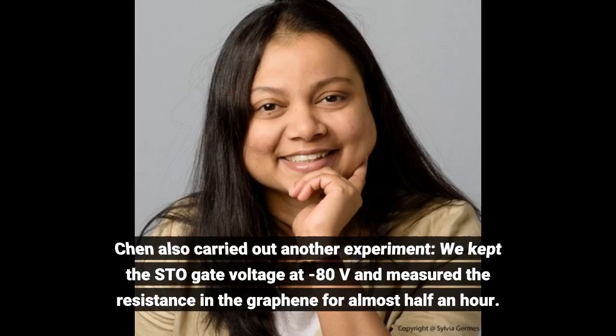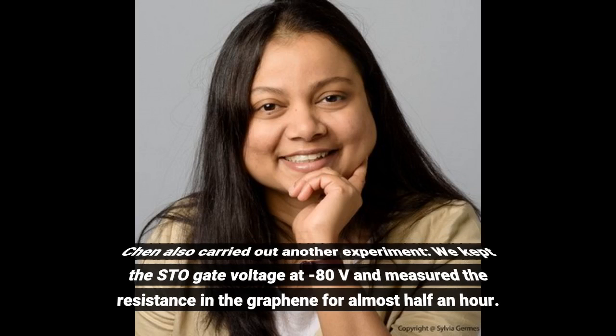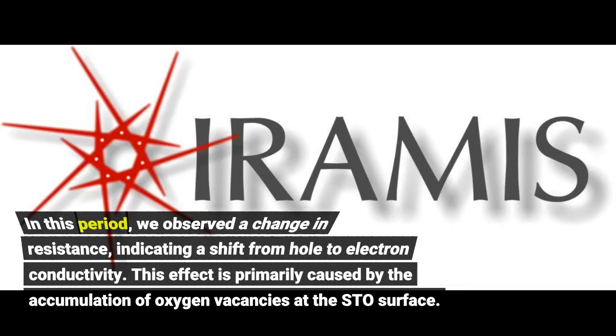Chen also carried out another experiment. We kept the STO gate voltage at -80 volts and measured the resistance in the graphene for almost half an hour. In this period, we observed a change in resistance, indicating a shift from hole to electron conductivity. This effect is primarily caused by the accumulation of oxygen vacancies at the STO surface.